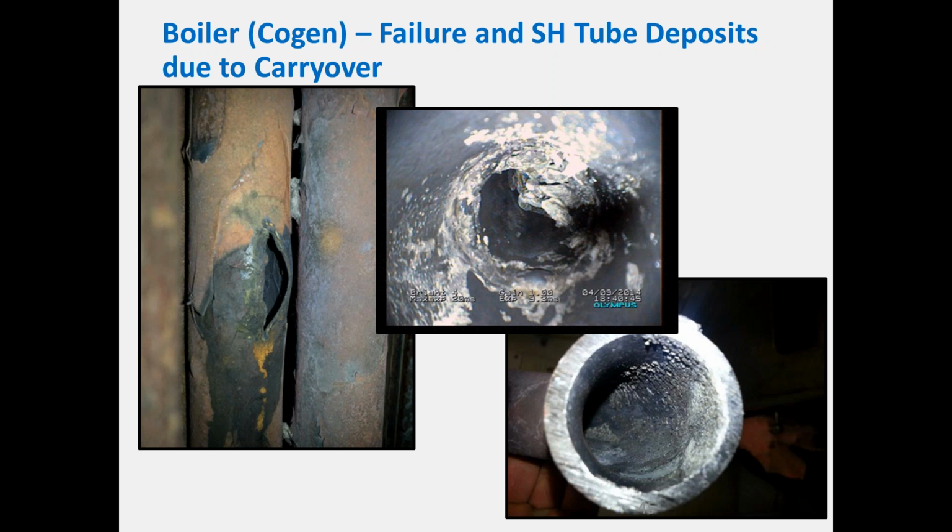Yeah, and the other one is if you've got even a small steam turbine, steam turbine repairs are very expensive. Even a 1 or 2 megawatt back pressure turbine: often, if you've had a deposit that's resulted in some corrosion damage, it can't be repaired in New Zealand.